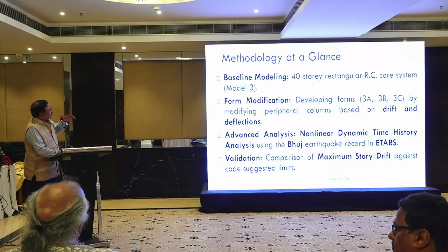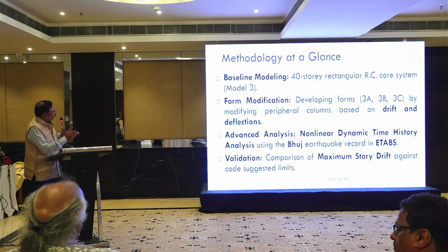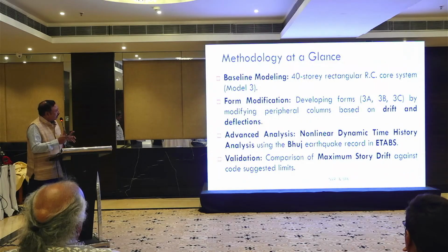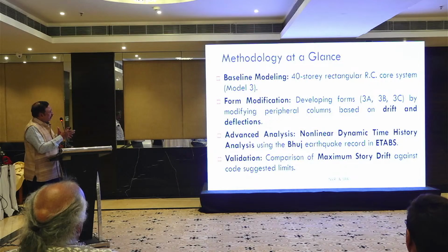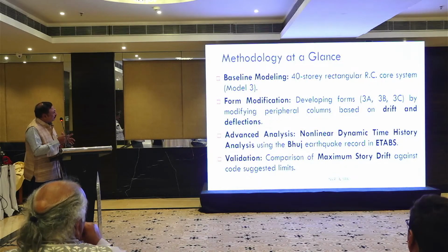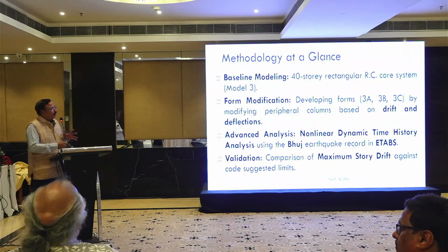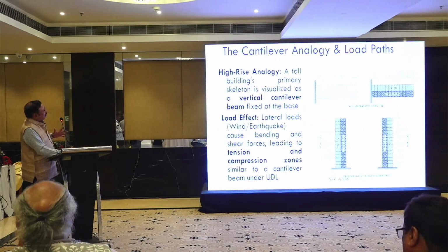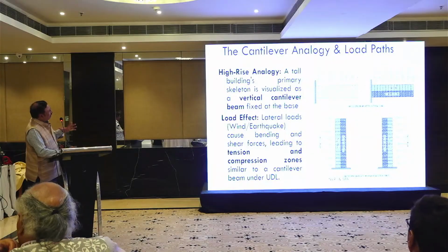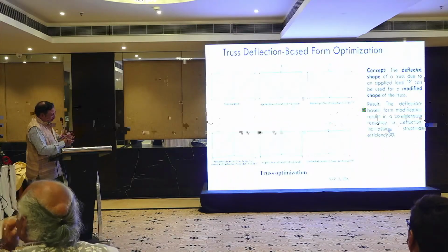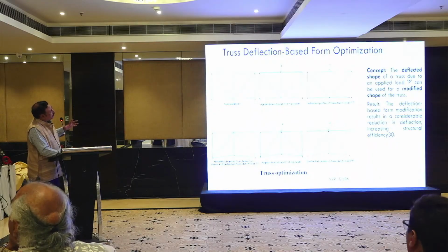So this was the idea: baseline, doing that, then slowly modify the shape and again study the analysis. Advanced, he did a non-linear dynamic time history analysis using ETABS. And then he's validating the results. Just running the computer is not enough. You will have to validate the results. So finally, he used the cantilever analogy and tried to arrive at the various... And it's a very interesting concept in optimization.